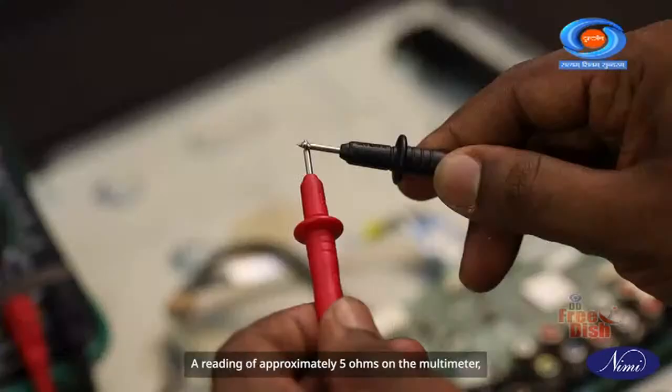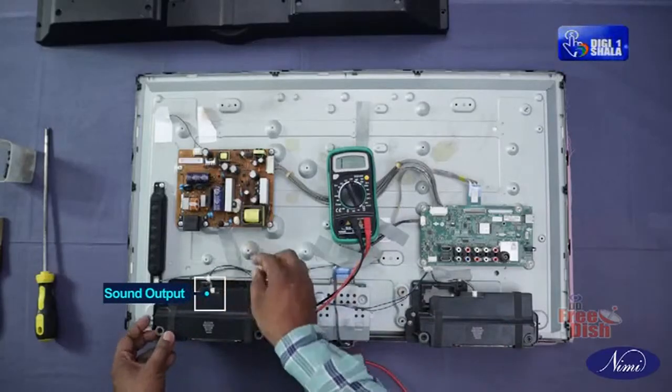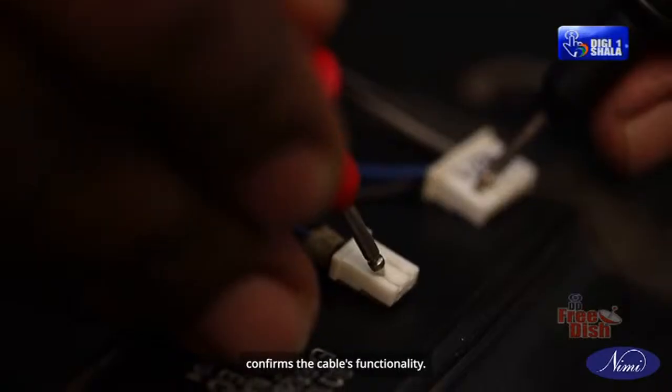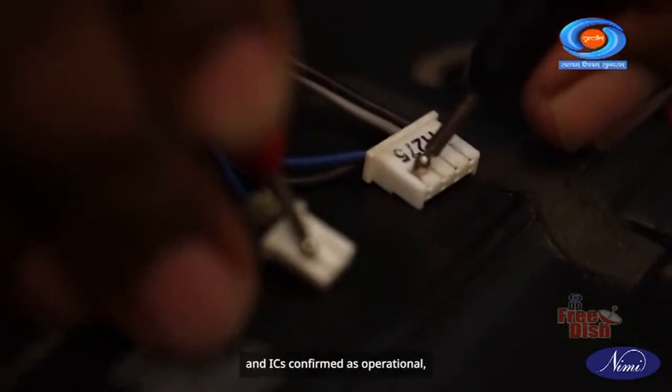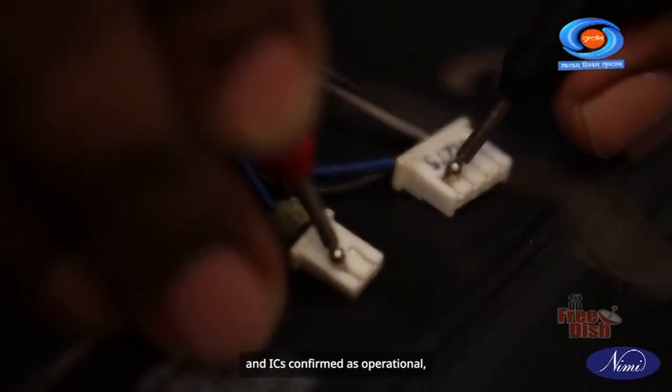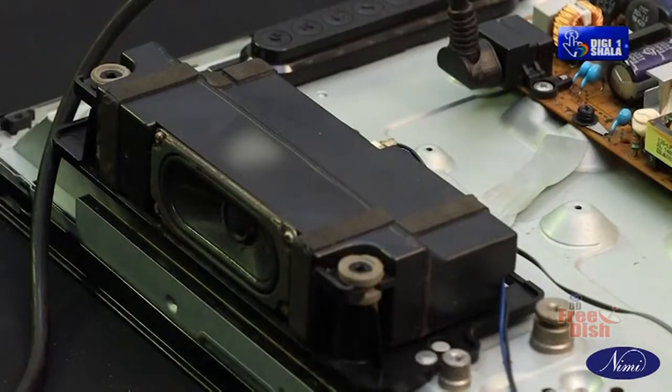A reading of approximately 5 ohms on the multimeter, accompanied by sound output, confirms the cable's functionality. Once the integrity of the cable is verified with the mainboard and ICs confirmed as operational, redirect your attention to testing the speaker unit itself.